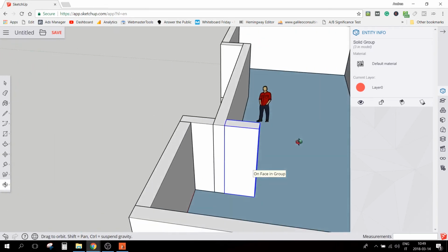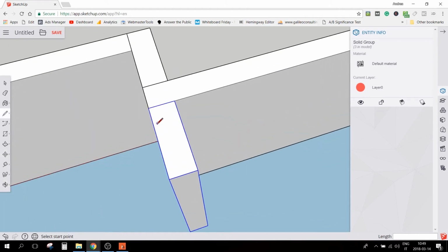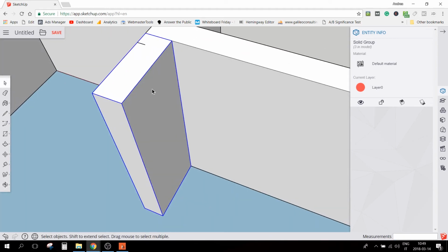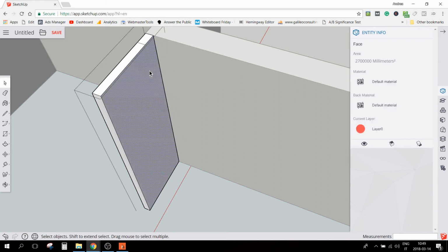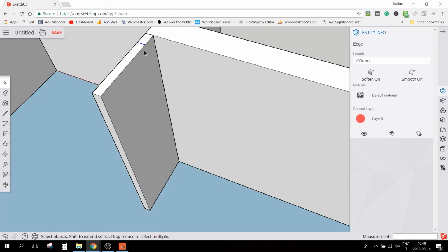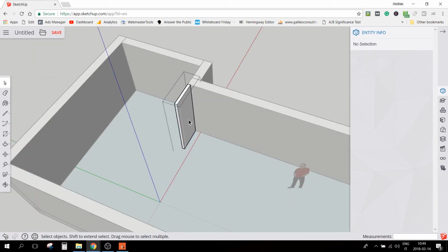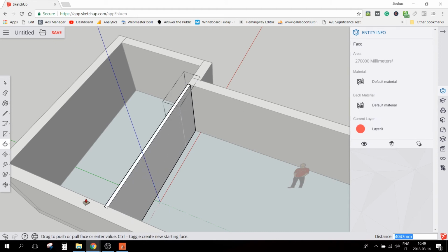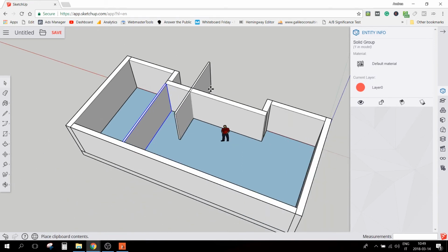so the internal wall of course has to be in line with this. So it will be like from here, let's make it 100. So we will open this object, double click and push this back to snap here. And then we click out, and then we select the line and remove it. And now we can extend this P here. Boom. And this we can copy and we can paste it here.